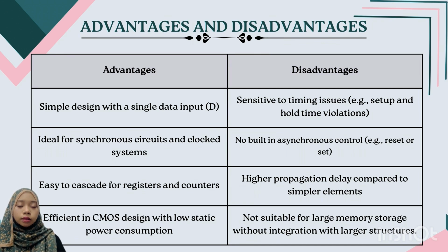The flip-flops are sensitive to timing issues, such as setup and hold time violations, which can cause incorrect data to be stored. They also lack built-in asynchronous control, meaning there is no default reset or set functionality unless additional circuitry is added. Compared to simple storage elements, the flip-flop has a higher propagation delay, which can affect the overall speed of the circuit. Lastly, they are not suitable for large memory storage on their own. To handle larger data storage needs, the flip-flop must be integrated into more complex structures.